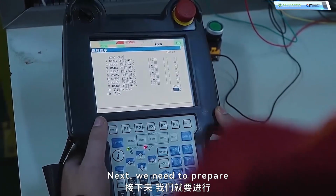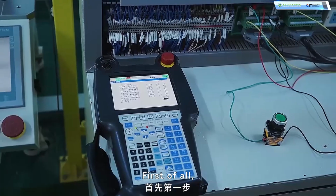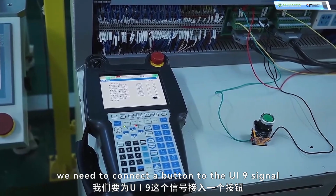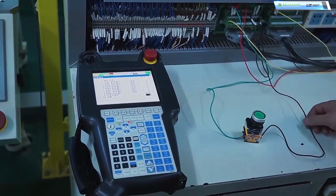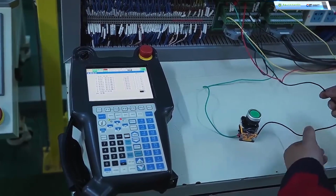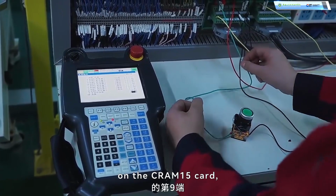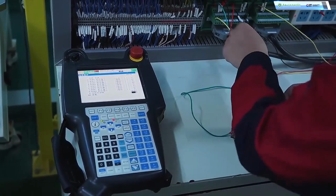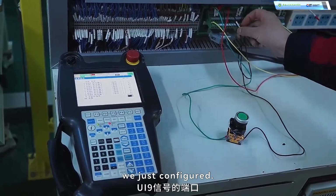Next, we need to prepare some external components. First of all, we need to connect a button to the UI9 signal for controlling the external RSR startup signal. As you can see, we connect this button to terminal 9 on the CRMA15 card, which is the port for the UI9 signal we just configured.